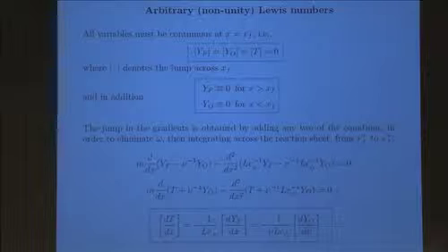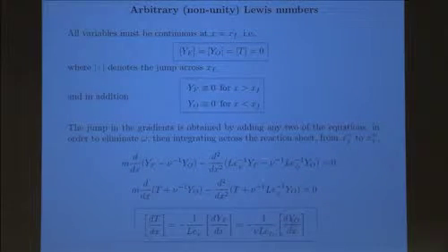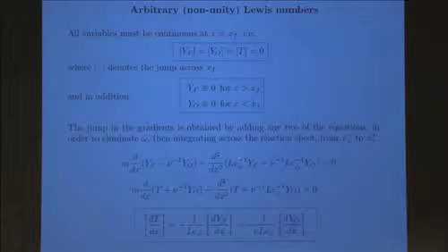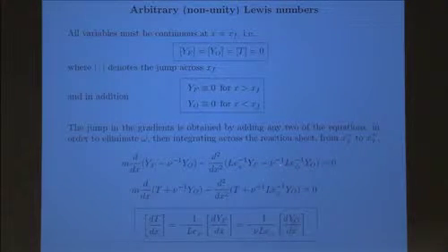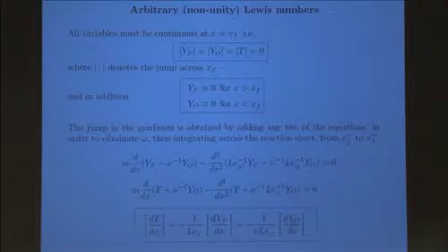If I integrate once, since these variables are continuous, that contribution is 0, and the only non-zero contribution comes from here. When you integrate once, you get the derivative, or the fluxes. So the flux of the fuel multiplied by the reciprocal of the Lewis number is equal to 1 over nu, the Lewis number of the oxidizer to minus 1, times the flux of YO, which is this part of the relation. In other words, those two fluxes are related. In fact, they are exactly in stoichiometric proportion.